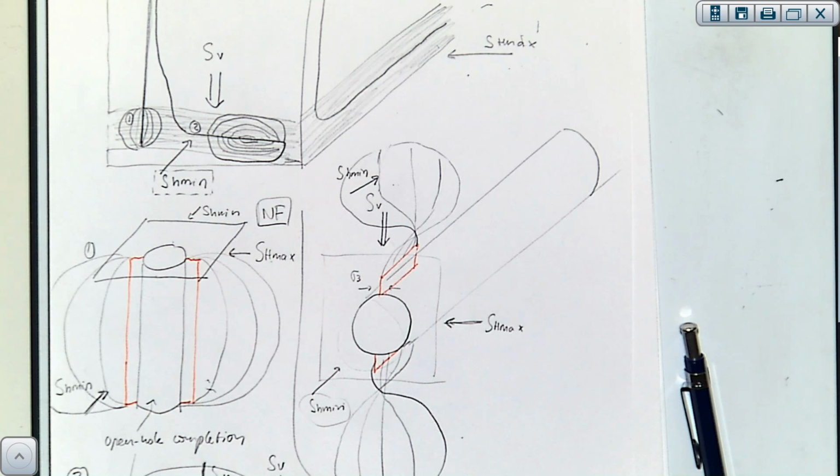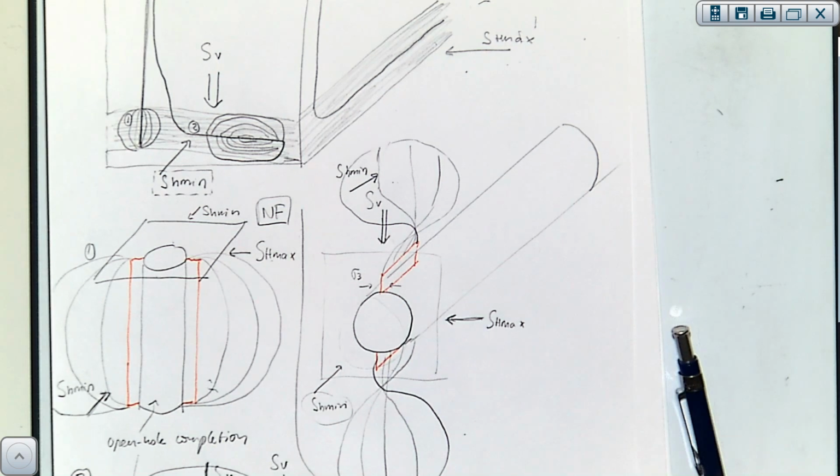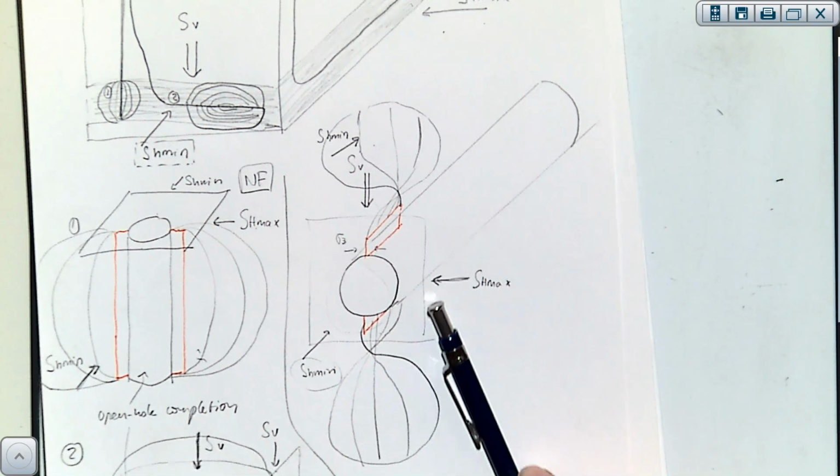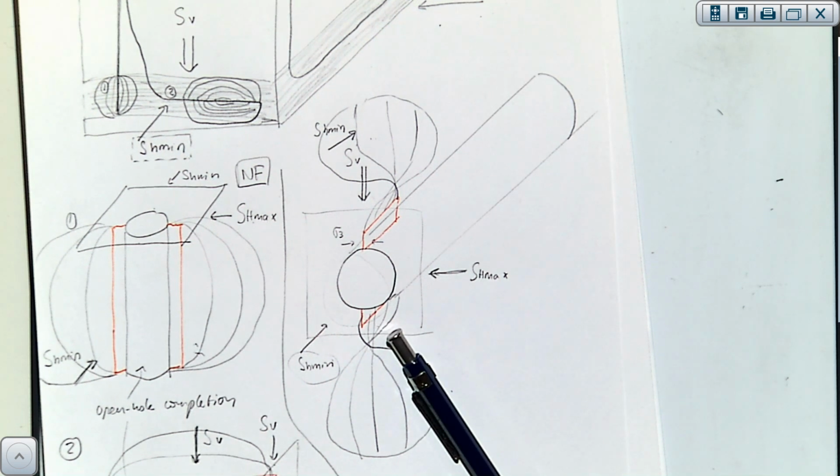That's what you want to say, Stephanie? So your fracturing fluid is kind of choking there. If you have proppants, those are going to screen out at that point. In reality, it's not going to be exactly like this, but it's going to be a complex fracture that at some point has to turn. And when that happens, that's not going to be good for the fracturing fluids or for the proppant. So this is not good.